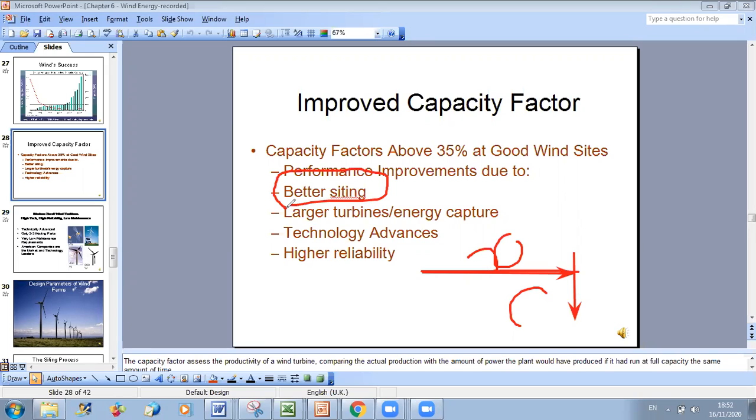Doctor, and also larger turbines allow for a larger blade diameter. Yes, right, the bigger they get, the bigger the blades they can use without disturbing the circulation. Of course. When we talk about a larger turbine, it's a higher diameter, yes, and it's a higher height too. When you have a higher height, you can avoid the effect of obstacles. Almost all the obstacles are below the wind, and this will ensure a better unidirectional flow that will hit your blades.